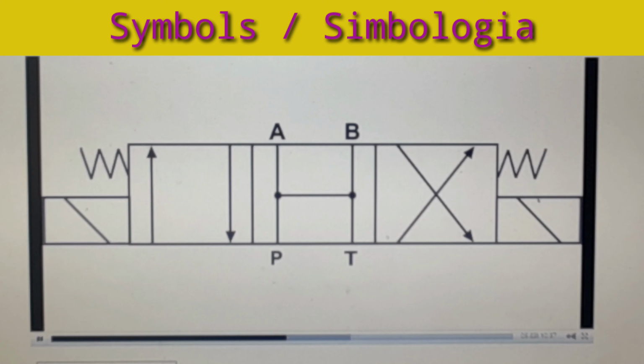Open center, where all 4 ports are connected together. Float center, where ports A, B, and T are all connected. Tandem center, where ports P and T are connected.